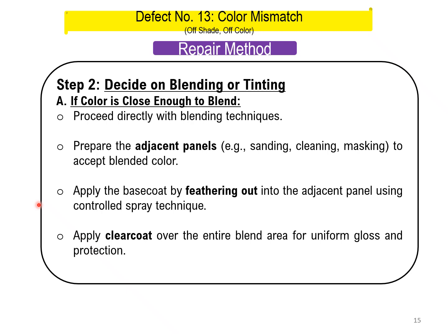Apply the base coat by feathering out into the adjacent panel using controlled spray technique. Apply clear coat over the entire blend area for uniform gloss and protection.